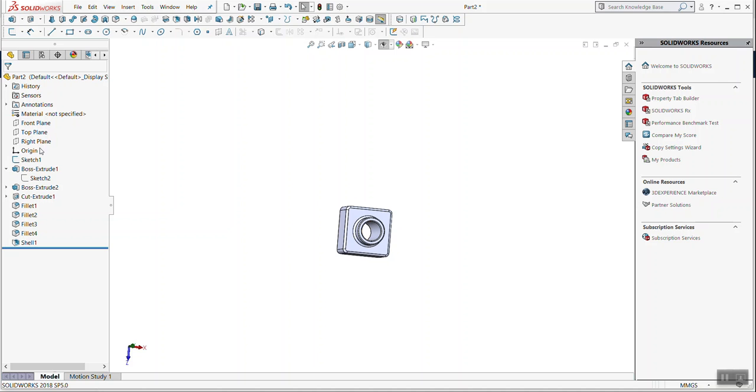So the step you probably skipped was you didn't make a new sketch and you didn't copy the features from that sketch. That also happened. So using a master sketch to build, it often happens at some point you might end up, yeah, I call it eating the sketch. You may end up eating the sketch at some point. Try and be aware of it.